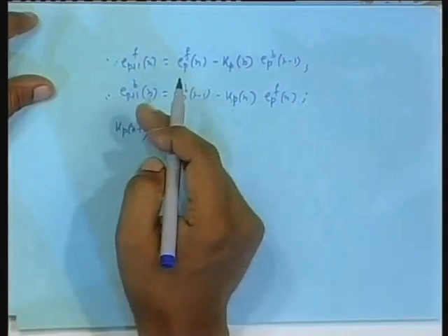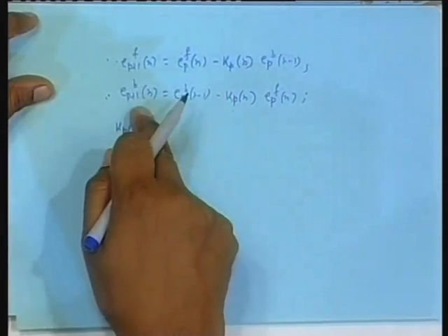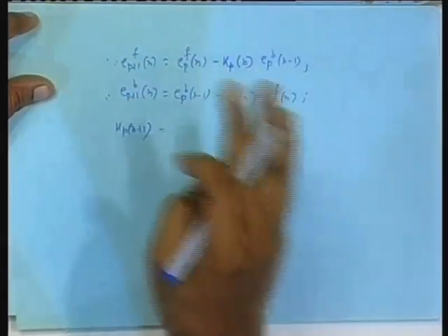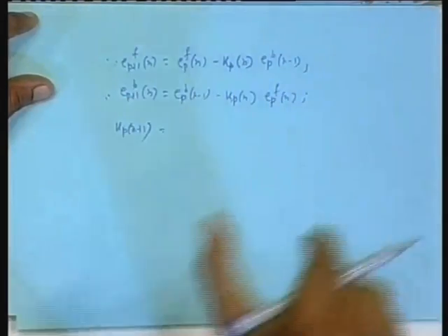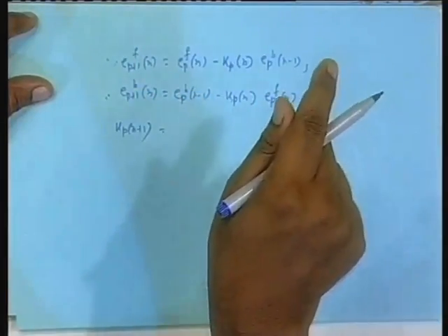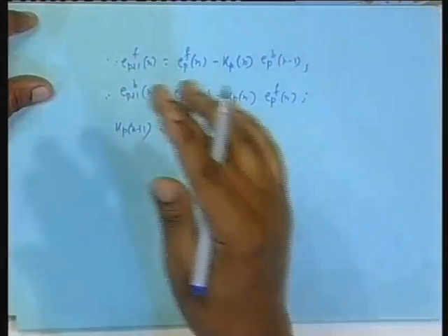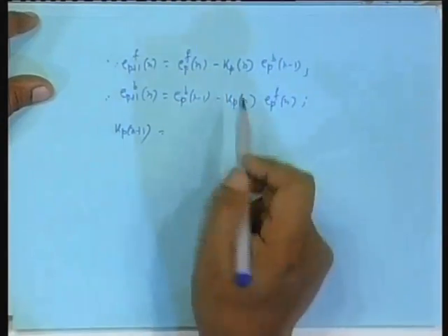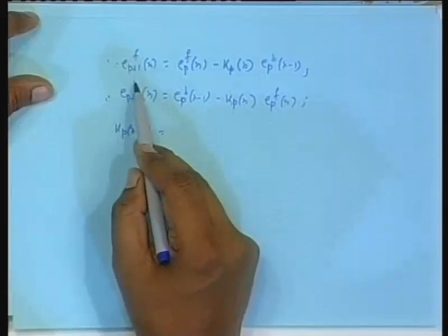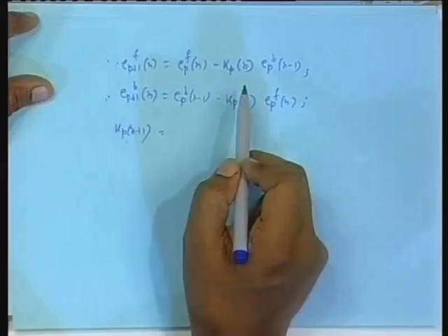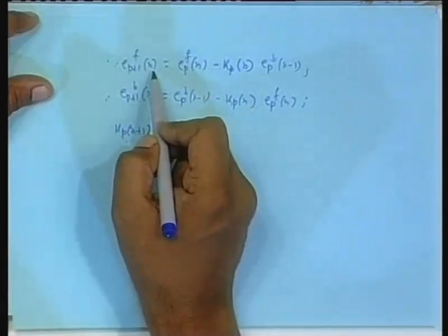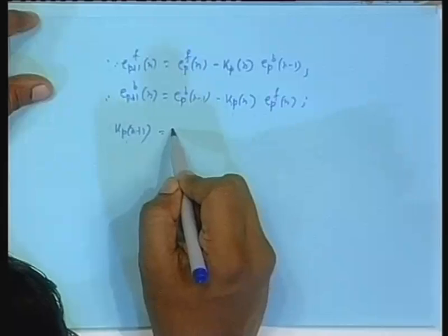This is adaptation. During adaptation also I continue to get these values, like in the case of LMS algorithm for optimal filter, for that transversal filter. During adaptation also, with those incorrect weights which are under training process, you get the filter output, and using that you get the error. That error you feed back in the LMS algorithm, get better coefficient. And similarly here also, using incorrect KPs you get them. Using this you get new coefficient. Then you again use that back to filter in the next time index n plus 1. You understand? So, this will be Kpn.